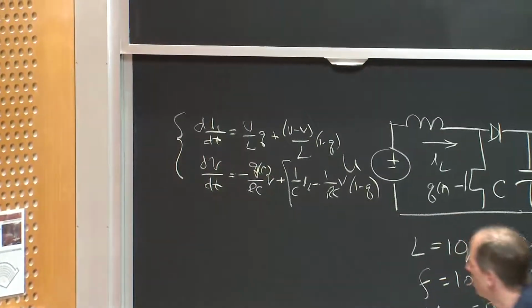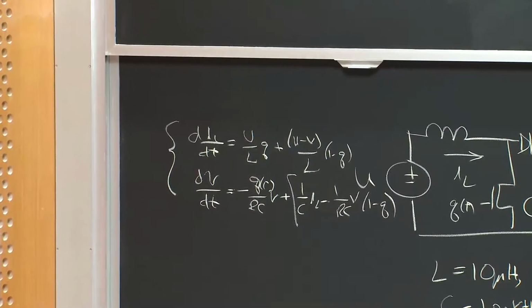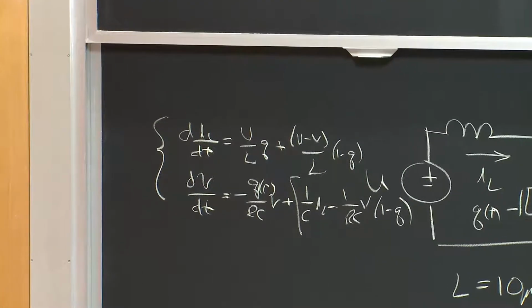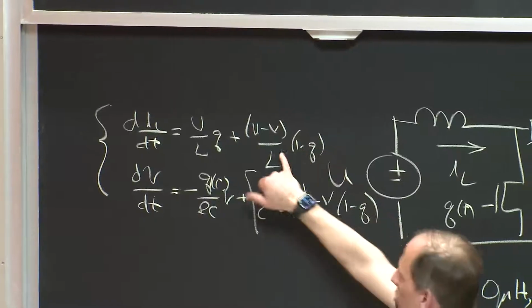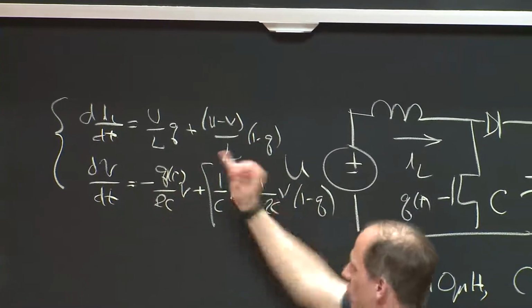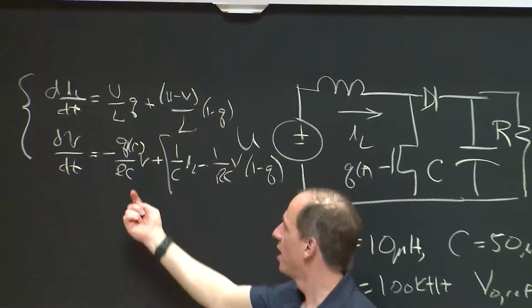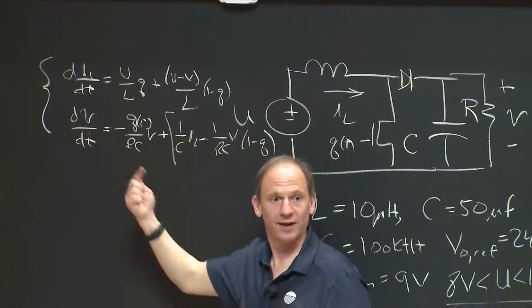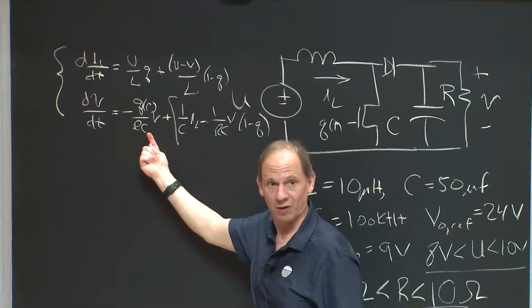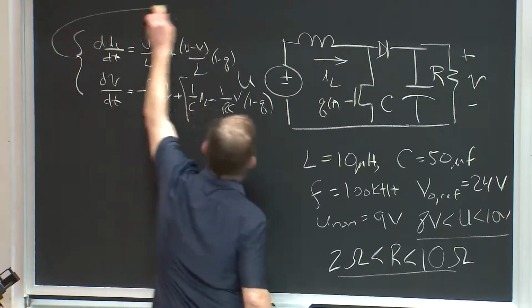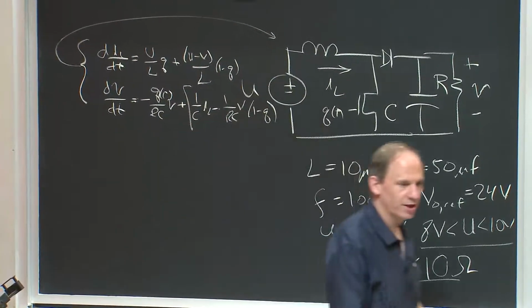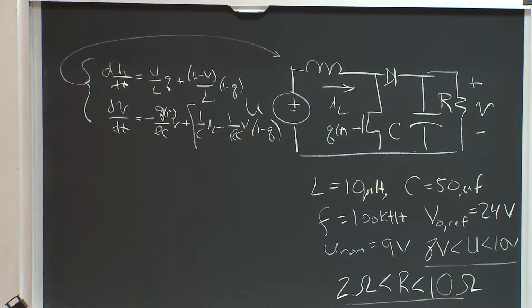Okay? So in this original model, all we've done is broken this down into 2 states and used my switching function to sort of switch back and forth between the states. And if I knew initial values for IL and V and I knew Q of T, how it was modulating, basically, at least in continuous conduction mode, I could exactly simulate the actual behavior of that converter.